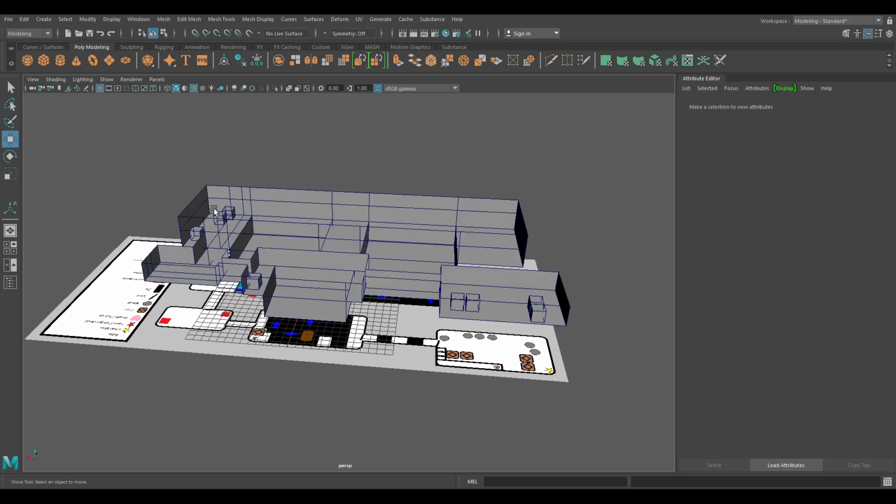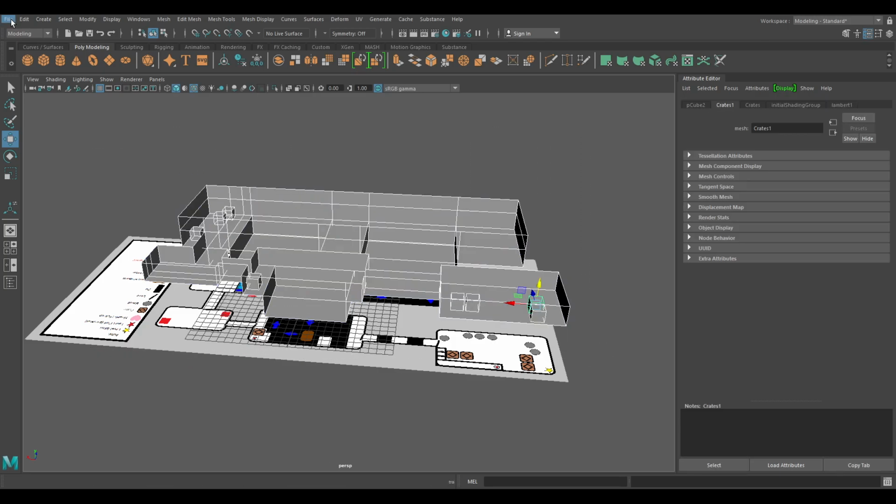And then we're ready. So I think the best thing for us to do is we drag select over everything, file, export selection. We're going to drop into options just to make sure everything's set up right. So we're going to go FBX, everything's fine. We should be good to go. So if we drop into here, just want to check our scale, make sure our units are going to be all right. At the moment, if you leave FBX, I've not checked this in Unreal 5 as of yet, but I know in Unreal 4, this has been an issue for me quite a lot.